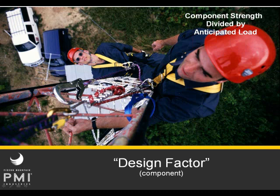Design factors that are common in life safety applications range from 2 to 1 up to 15 to 1. So this means that the item would be 2 times to 15 times stronger than the load you expect to put on it. In the case of rope, you can expect a 20 to 30% decrease in strength when you introduce a knot. There are other decreases in strength that occur based on other elements of the system. So how much the design factor matters as compared to the overall system is somewhat negligible.